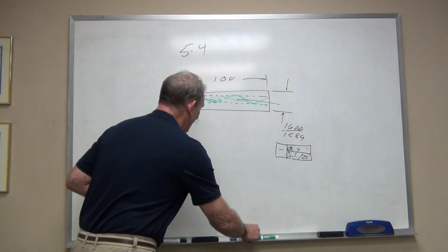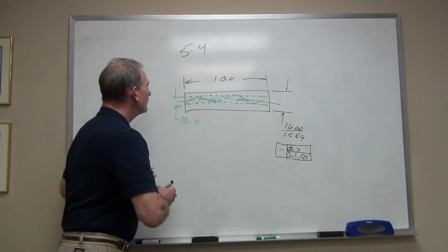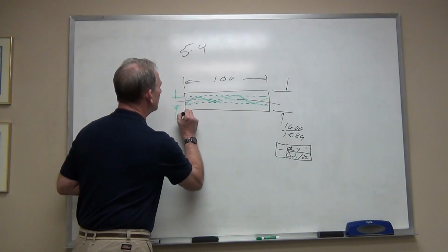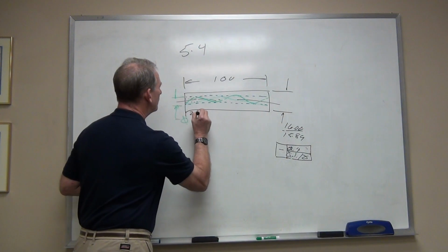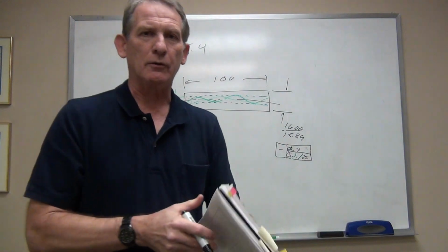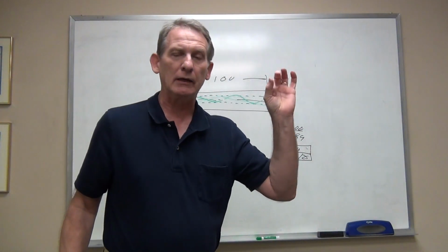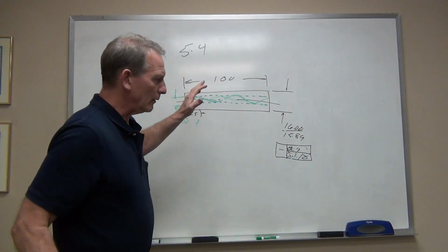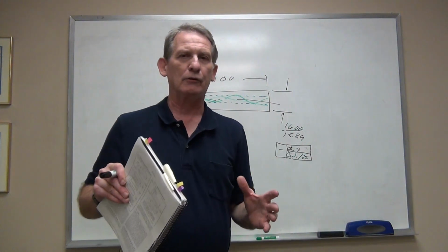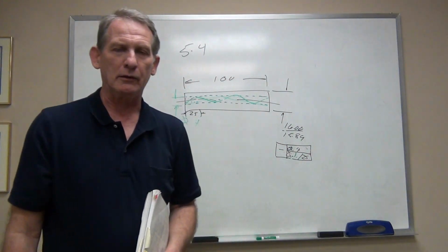So in that larger tolerance zone, we have a nested or embedded smaller tolerance zone that's a quarter of the size. What that effectively does is say that yes, you can have all that tolerance, but it has to be distributed somewhat evenly over the length of the part.